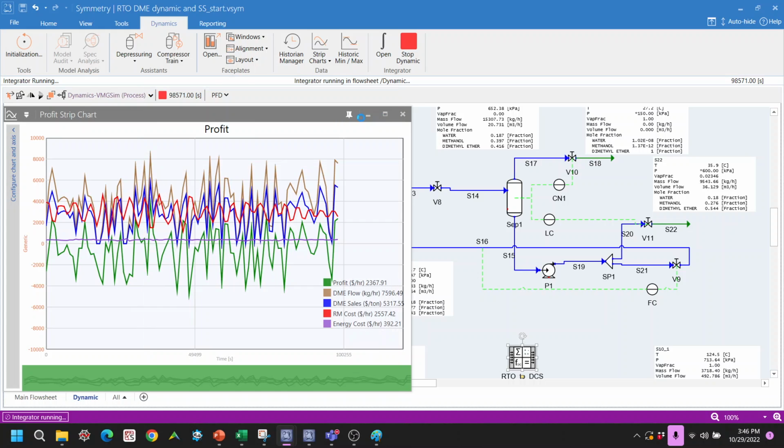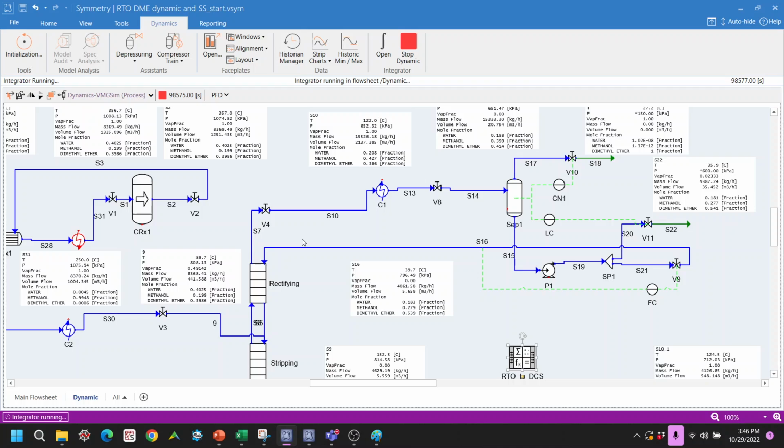But in this plant model, can we set a constraint saying max profit, and ask it to change at one certain point? No, we don't do dynamic optimization. There's no such thing. We have to get one snapshot of time and optimize using that particular data. That's why the RTO I mentioned is a steady state model.